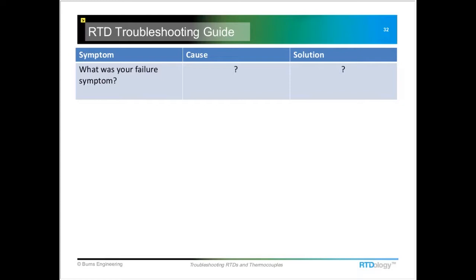Well, if it were the thermocouple, it would change, and it wouldn't change back. There's really no way I can see where it would change its voltage back and forth like that. And it sounds like this is a pretty regular occurrence. If it were just once, I might say maybe a lead wire is starting to break or something, but that's pretty rare in a thermocouple. And this just seems like it's something to do with some kind of stray voltage or RFI, EMI type stuff.